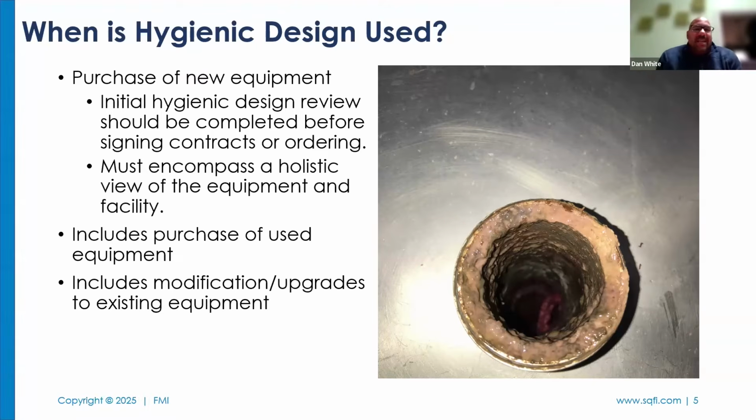So when is hygienic design used? When you purchase new equipment, and we should say used equipment that is new to you, the initial hygienic design review should actually start before you sign contracts and order that piece of equipment. We all work really, really hard to get that CapEx to order the piece of equipment that we've wanted forever. It's going to improve every aspect of our lives. And then sometimes it shows up and it's not what we wanted or needed. So you actually need to start that hygienic design review before you actually get that piece of equipment.